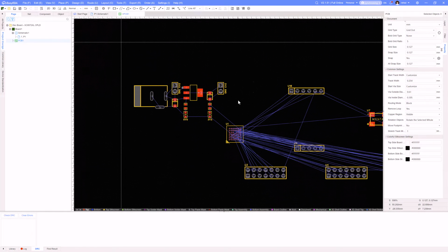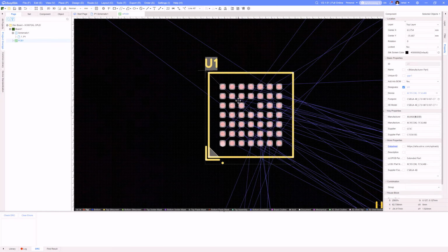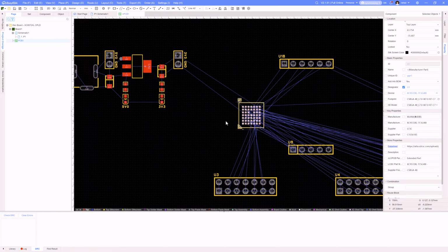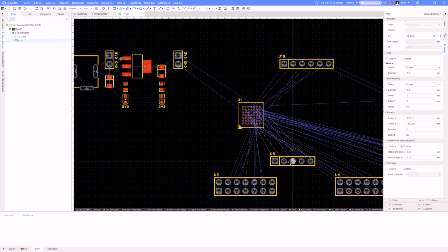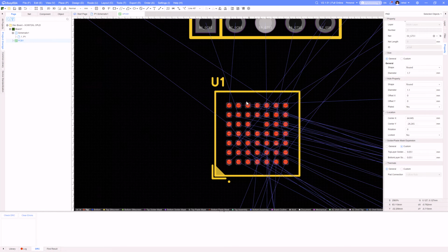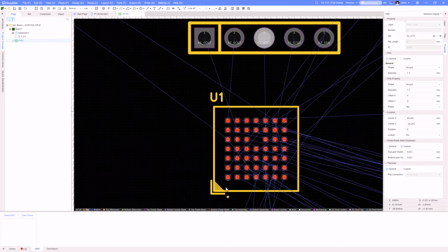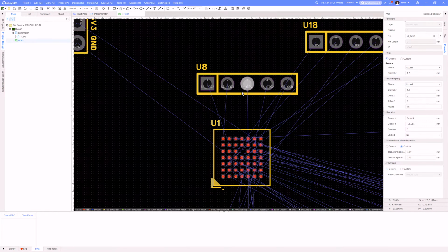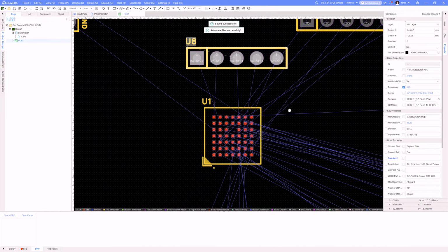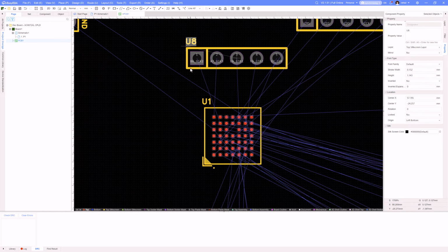Okay. Then I've got this. This is the main IC I'm going to work with, a BGA CPLD. And as I move this, I can see all of these are towards this side of it. Looks like pin 1 of the package they're considering down here. And I'm going to put this on this side of it. I think that will be fine.